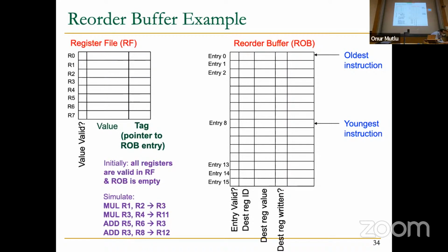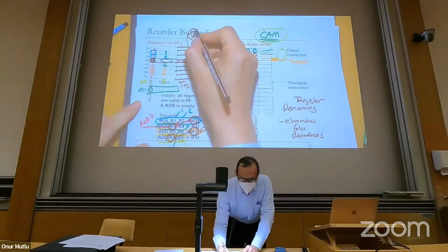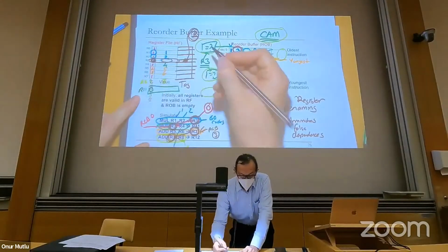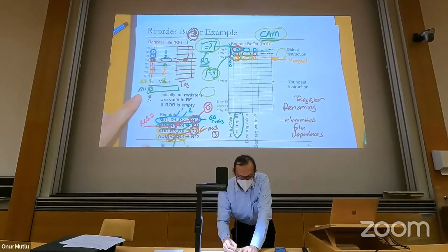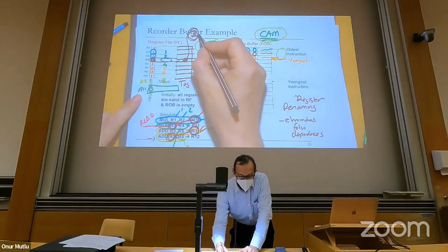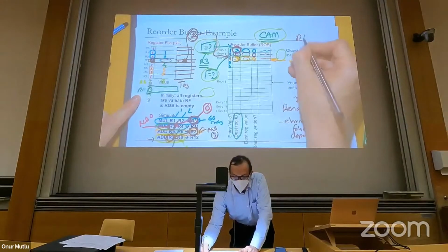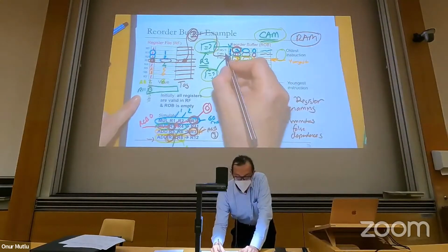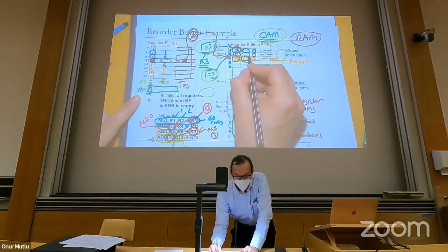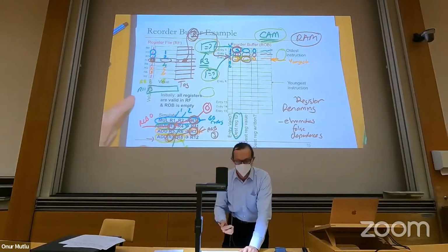So let me go back over here again. Sorry for this frequent back and forth, but basically this says 2. While decoding this latest instruction, you take this address to index the reorder buffer, just like a random access memory, meaning not a content addressable search, and basically get the value if it's available over there. Otherwise, you'll stall until the value becomes available.